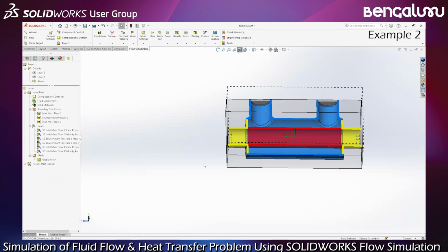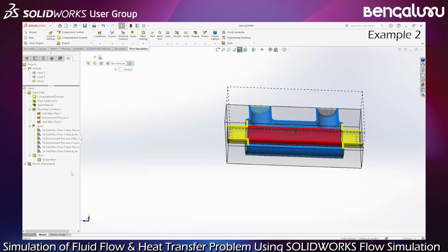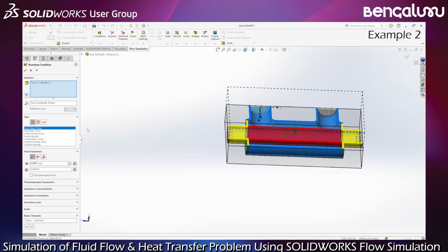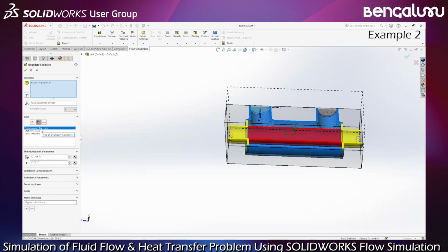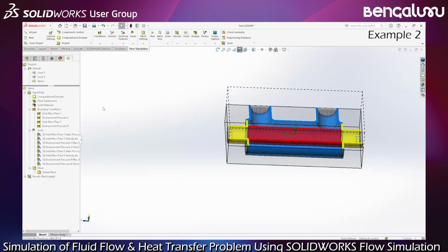And the last one is this face, where I have to select which type of condition. It's environment pressure, and maybe a goal to make sure that the conservation of the mass flow rate holds, and as well velocity, for example, why not? So automatically I have set conditions and goals. And we saw last week as well, we can deal with equations if you want to get a given scalar value of something. Just use a formula and you get it.